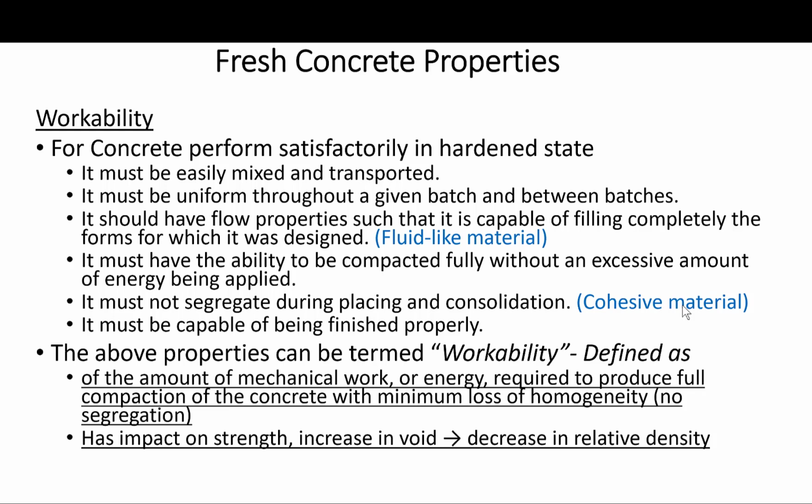It should have flow properties such that it is capable of filling completely the forms for which it was designed. It must have the ability to be compacted fully without an excessive amount of energy being applied. Easily compacted. It must not segregate during placing and consolidation. It must be capable of being finished properly, either against the form or by means of a traveling or other surface treatment.